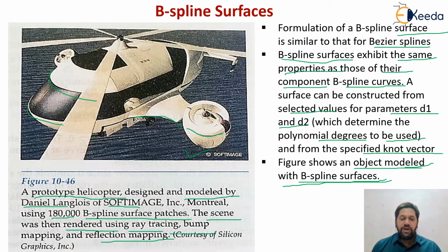In today's session, starting with the advantages of the B-spline curve, we have seen there are two advantages of the B-spline curve as compared to the Bezier curve, but B-spline curves are a little bit more complex than the Bezier curve. Then we have seen how it will look depending upon its values. Then we have seen the different properties of the B-spline curve. There are 7 properties that we have considered. Then we considered the uniform periodic B-spline curve, its algorithm and its diagram. Then we have also seen what the closed B-spline curve looks like.